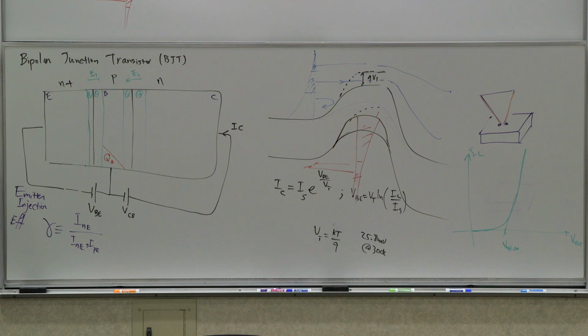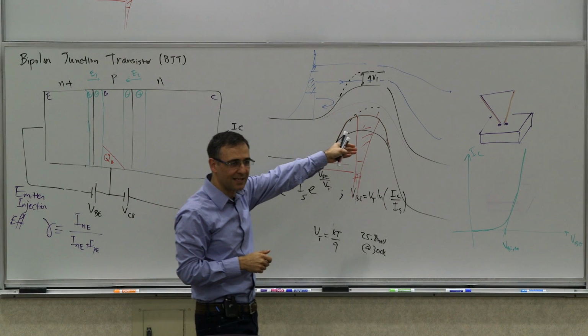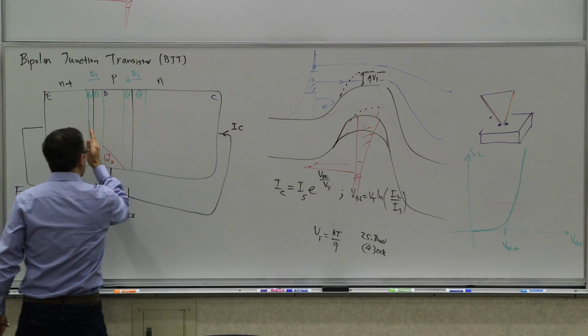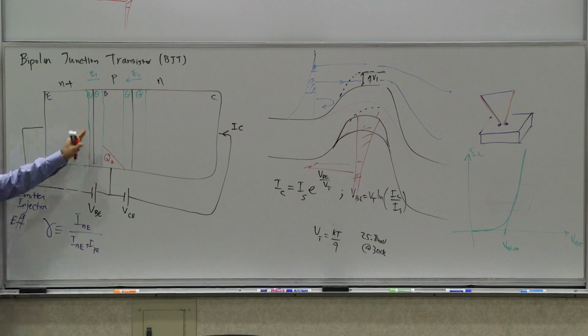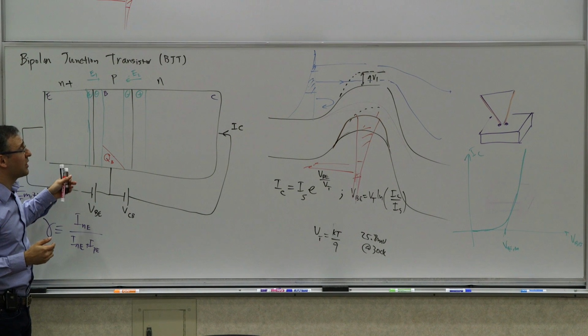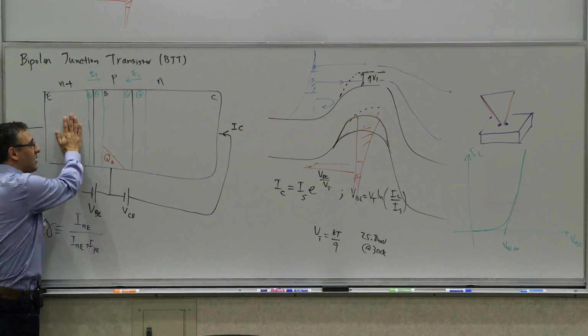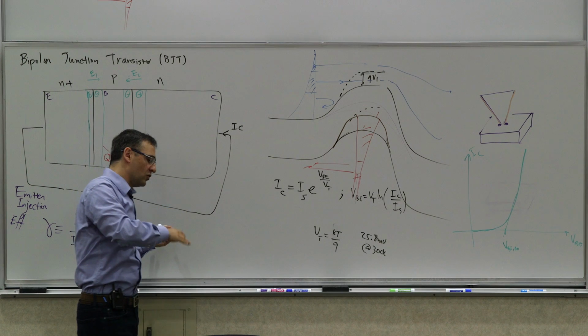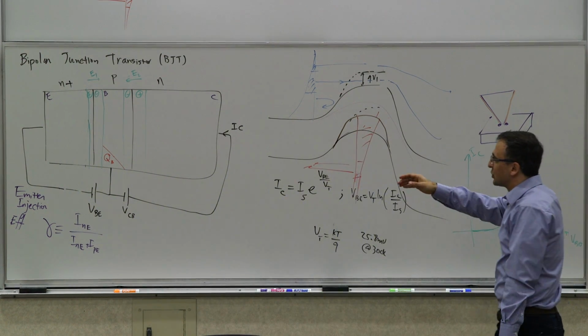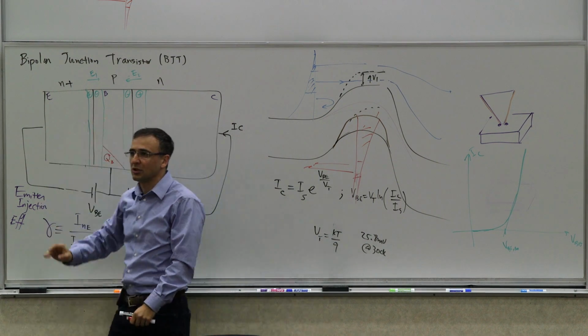So this is called HBTs, heterojunction, as opposed to homojunction, which is basically made of all the same semiconductor. You have a heterojunction, which is made out of different semiconductors, and it's very common. The other combination is that they make it gallium arsenide, aluminum arsenide, gallium indium arsenide, or indium phosphide transistors. They actually can engineer the composition of these things.